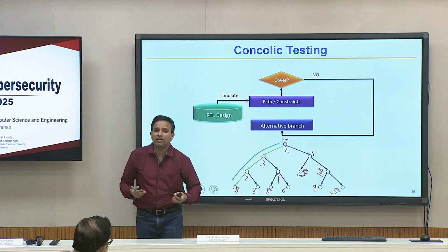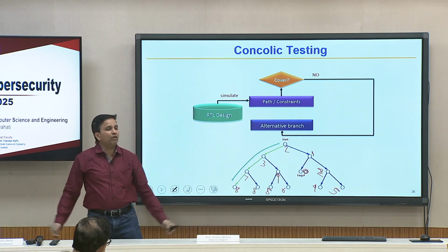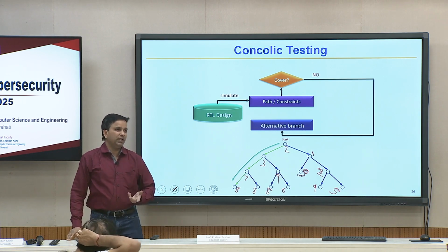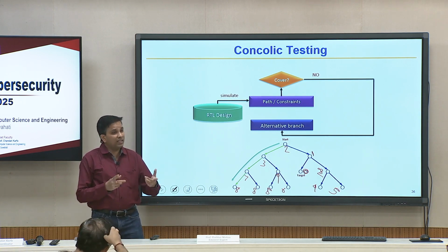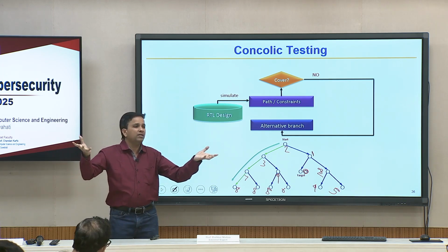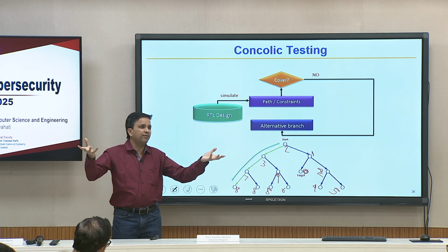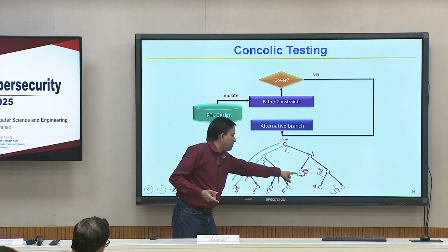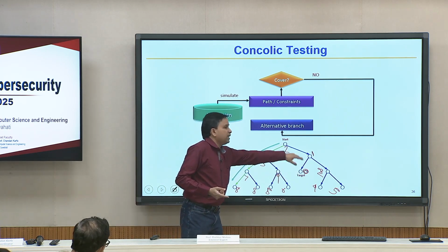This idea works if you can completely unroll the control flow graph, the CDFG. Unfortunately, we cannot do that. In a software design it is still easy, but in a hardware design you have multiple parallel control flow graphs, and this target may look close but may not be activable in 2 cycles.